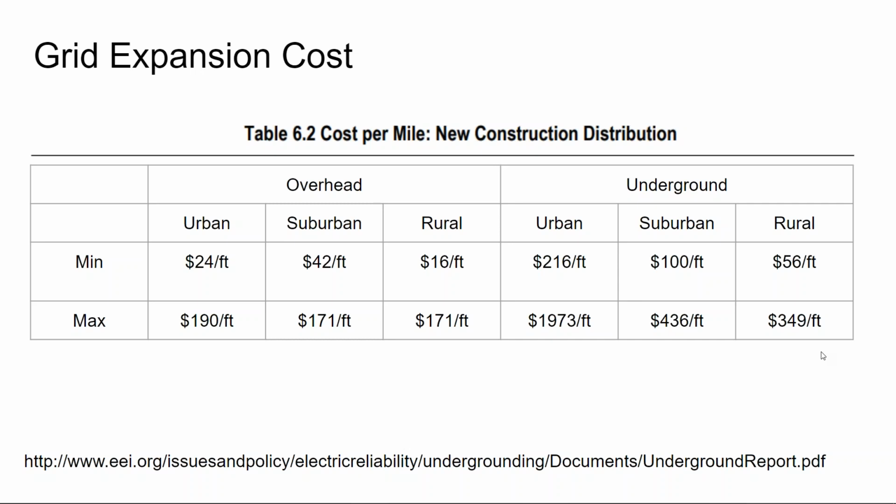So the grid can charge the battery, but the output from the system goes directly into the home and is not physically interconnected to the grid at all, other than on the input side where the battery charger is. So it's like the grid now charges a battery, and then the system supplies power to the home from the battery. We'll talk about those strategies as we move forward.